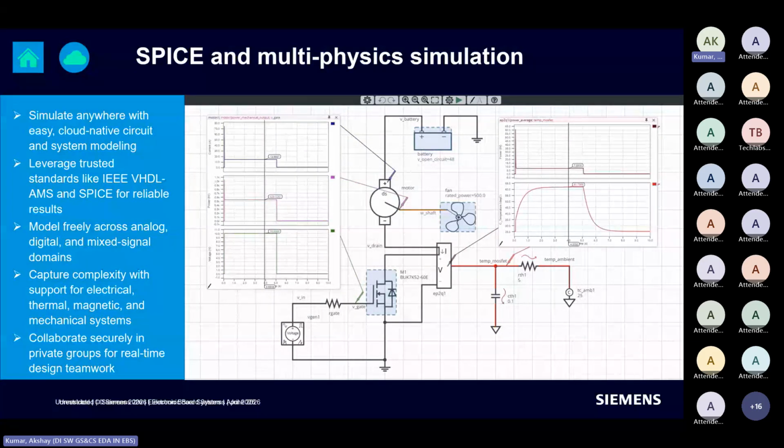Earlier, for the component information or the component library, we had the PartQuest solution, and this is for simulation purposes. So we have PartQuest Explorer as a solution, where you can simulate the design that you are looking for. And if the results are meaningful for you, if you feel that your analysis result is perfectly fine, then you can also integrate this cloud solution from PartQuest Explorer to the Expedition Designer as well.